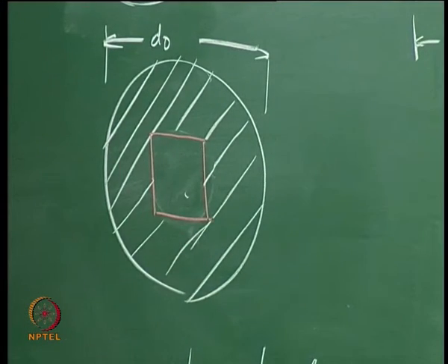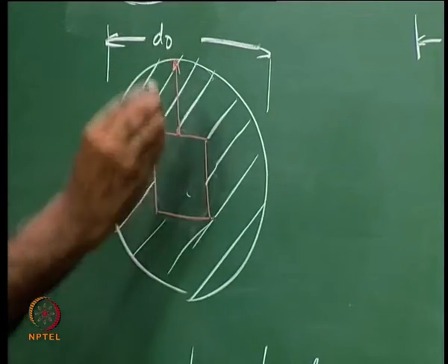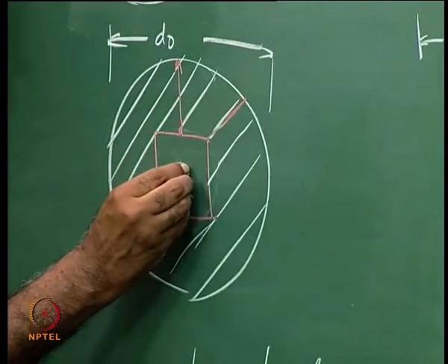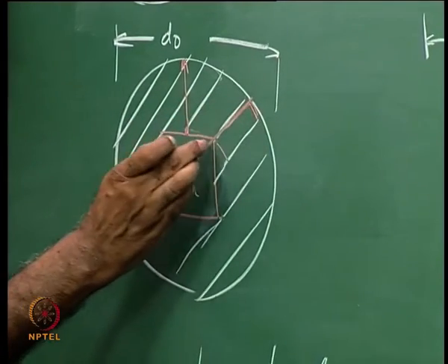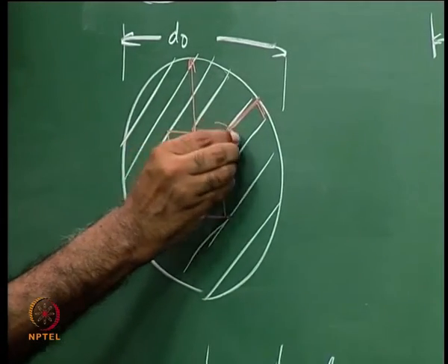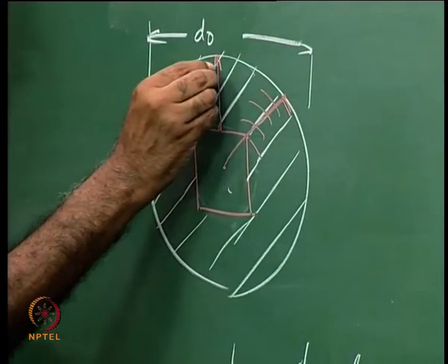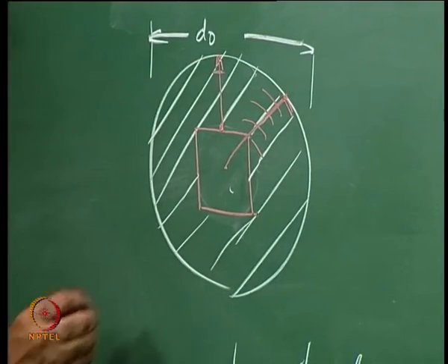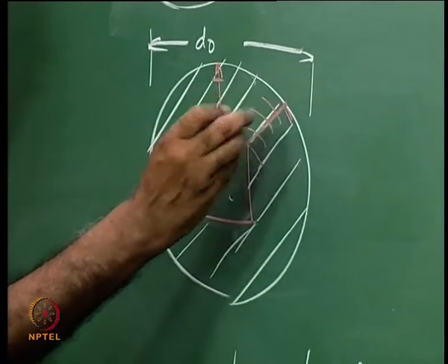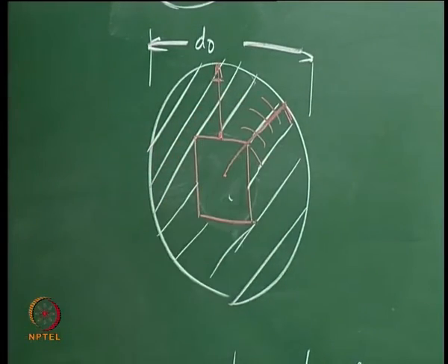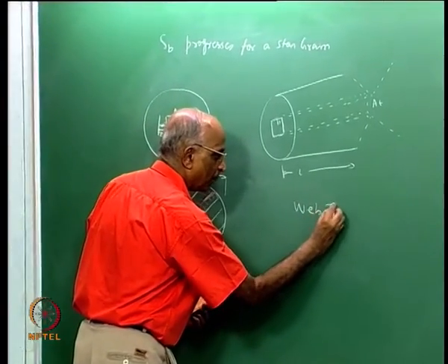Now what are the thicknesses I can talk of? This thickness is a little larger. This along the vertex, maybe from here if I plot a line, this is the minimum distance, and as the grain evolves it goes as a circle and first touches here, because here the thickness is larger. At that point it is coming only over here, and therefore this thickness between this point to the casing is the minimum thickness, and this minimum thickness is what is known as a web thickness.